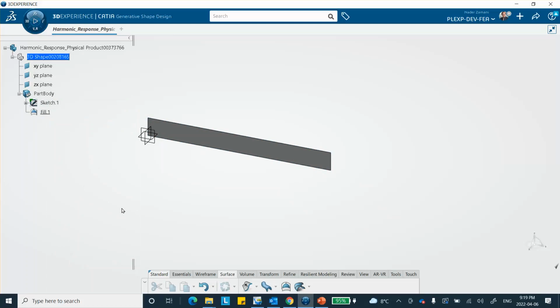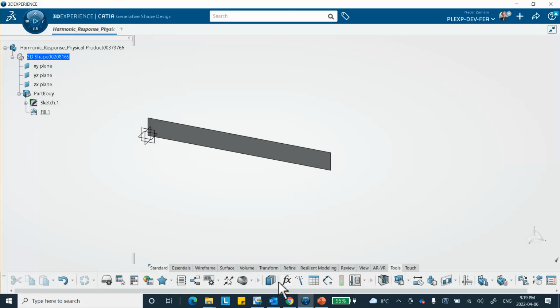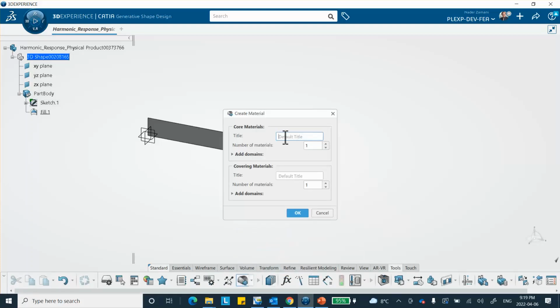Okay. Now let's create our material properties. So we're going to go to tools, create material. Let me call this thing, I don't know, harmonic. This is just a name. Harmonic response video. All right.